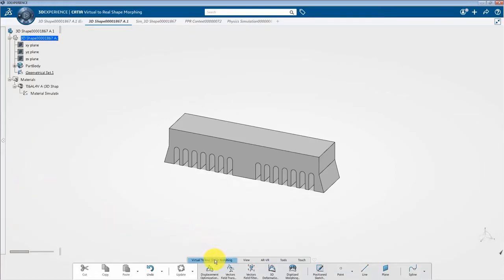Basically, this is an established technology, but we are finding that its capabilities are providing a lot of value in the AM space. So using this tool, we can morph a CAD object using process simulation distortion results and compare a deviation analysis of simulation results with experimentally obtained measurements. So this allows validating our process simulation distortion results with experiments.